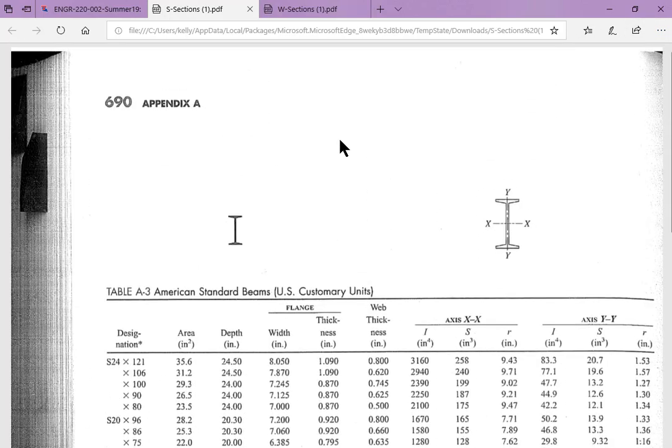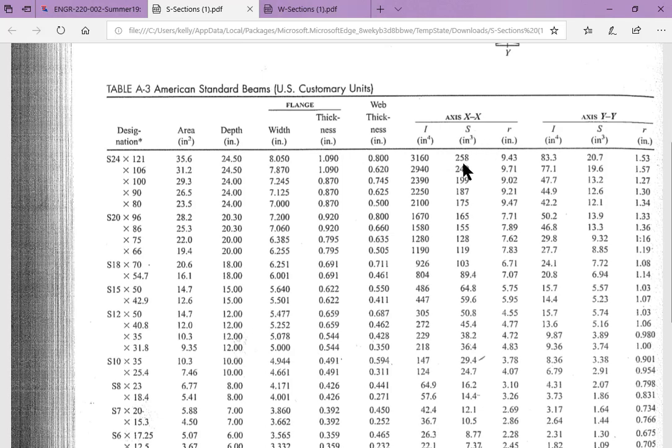All right. So C under this column, XX and YY. Also, the YY also has this if the beam is loaded sideways. There's this S column, and it's units of inches cubed because you would be dividing Y over I, or well, I over Y actually, to create inches cubed. And you get this number. And so this number is the section modulus for any of these beams.